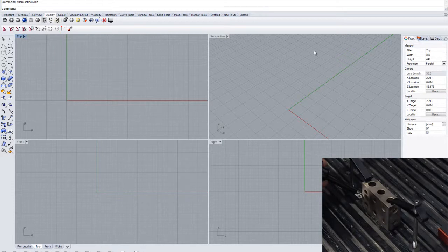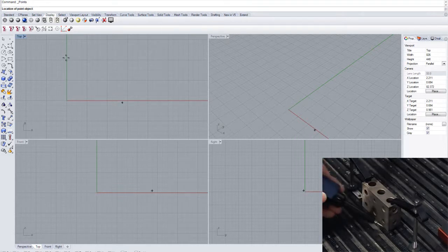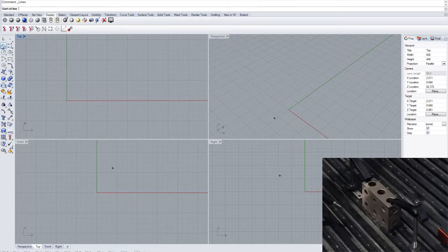So now we'll be able to use the coordinate system of the Rhino software to do some of our design work. So just for grins and giggles real quick, let's jump onto a set of points, and let's just move the probe along to check it in X and check it in Y, and we are absolutely aligned. So let's get started digitizing our part. Come over here to Align command.